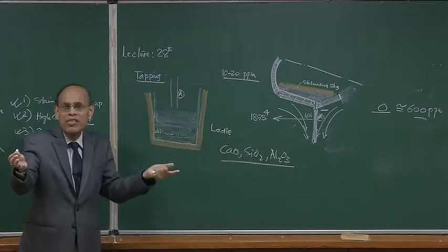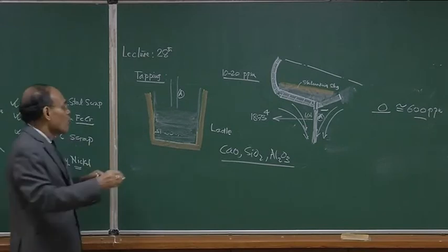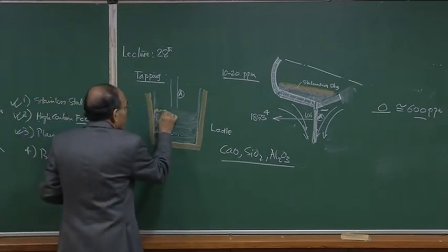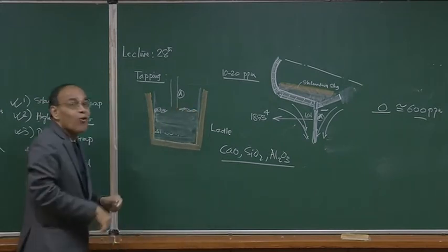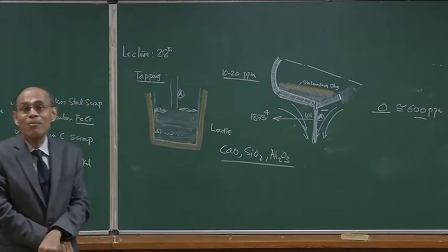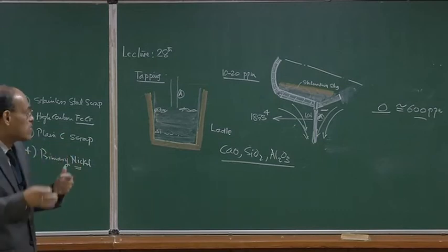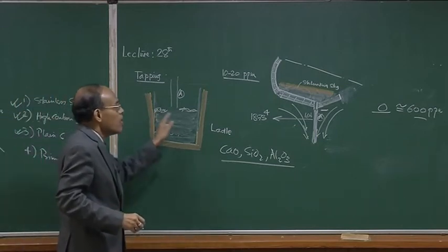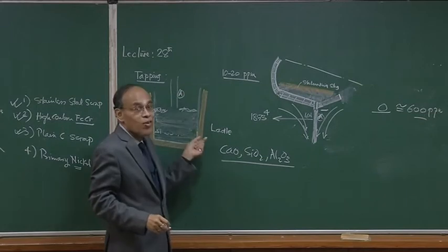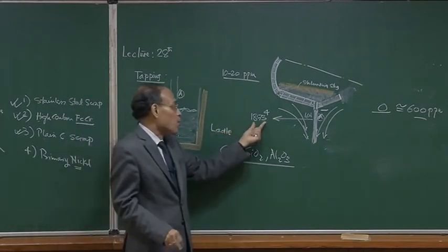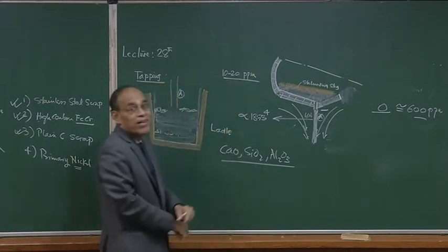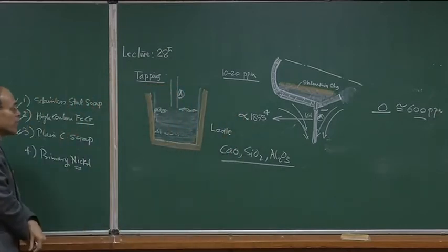So, in no time, a slag is going to form and the slag is going to be floating on the free surface itself. This synthetically prepared slag is very important for us, because it protects against heat loss from the system, because otherwise heat will be radiating during the process. Heat radiation is proportional to absolute temperature raised to the power 4, as per Stefan's law.